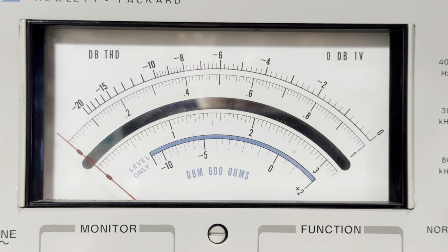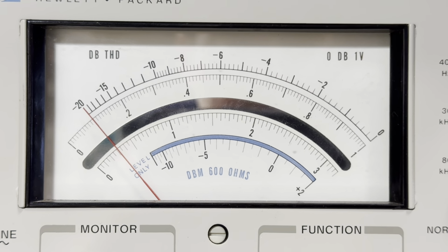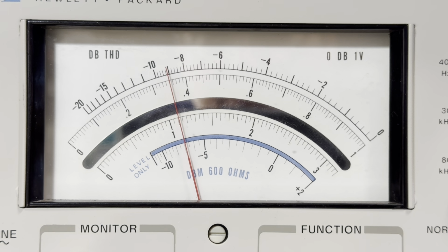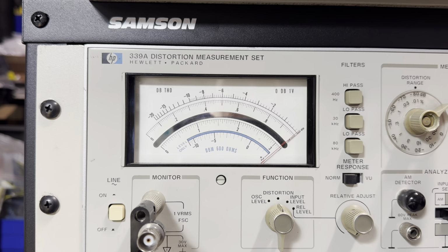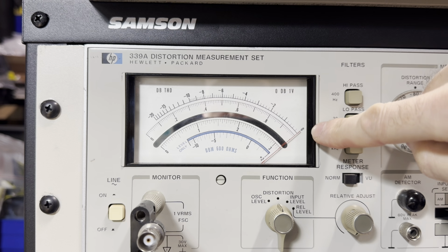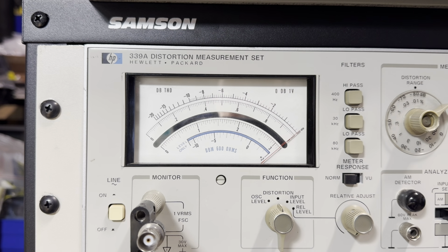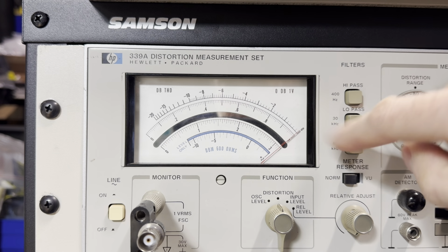Now looking at the signal on the HP339, and we can downrange. As we see now, we're starting to come on scale. We're at minus 60 dB on the range, and there is our signal. So we can see that we're just now on the lowest range of our measurement. We don't have any of the filters in right now, and we're just now at minus 80 dB. So that is our measurement. Our total harmonic distortion plus noise is there.